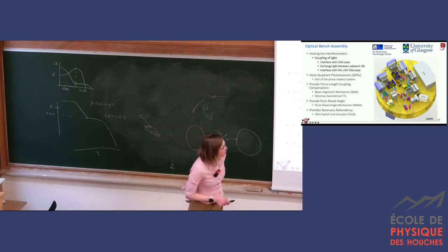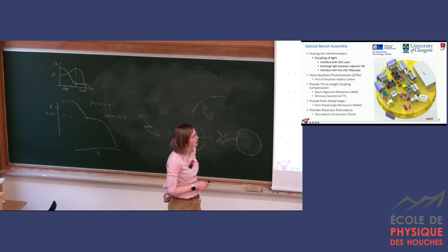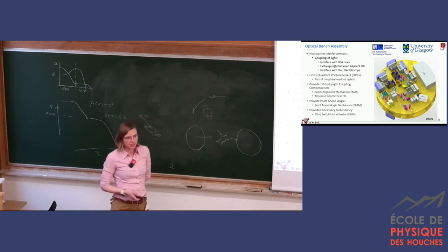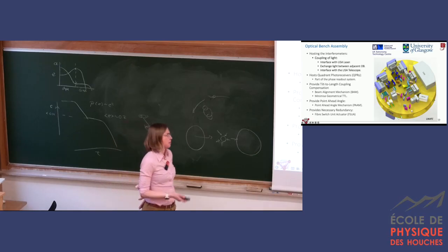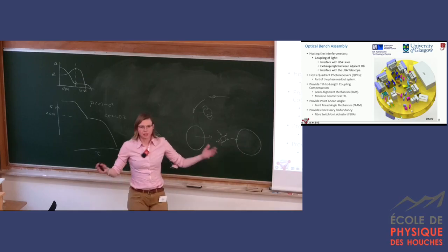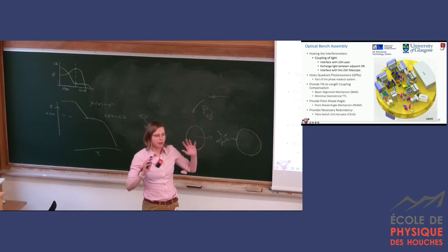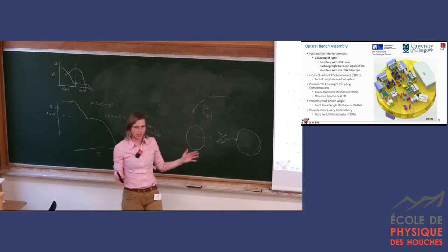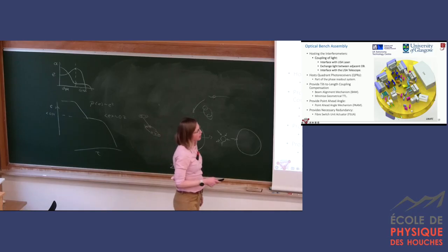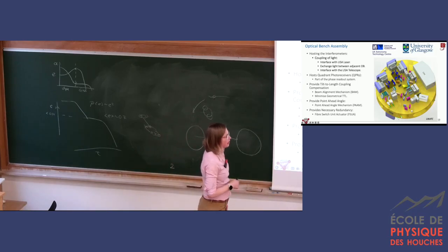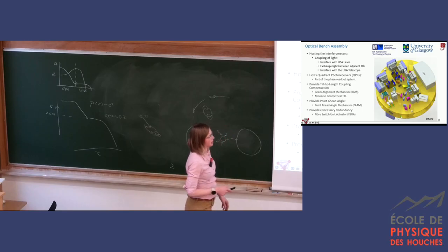And the first thing you can see here is this big blob, which is called CAS, Constellation Acquisition Sensor. Not going to be talking much about it, but this is the very wide angle camera that initially captures the RX beam. It supports the very first coarse acquisition of the constellation. And this is provided by the European Space Agency.